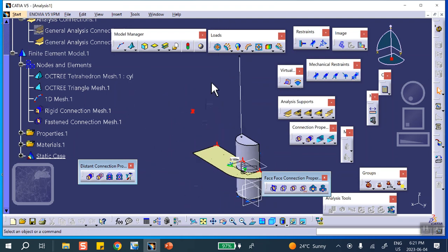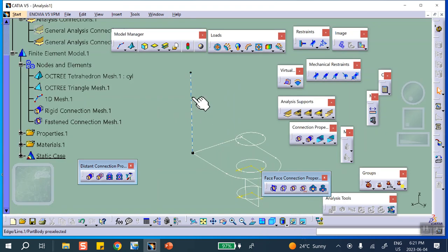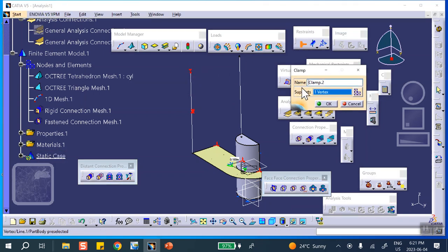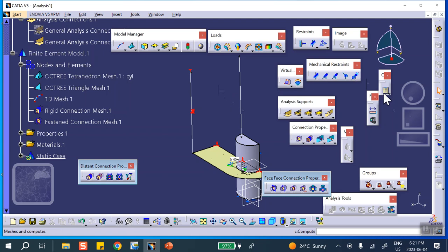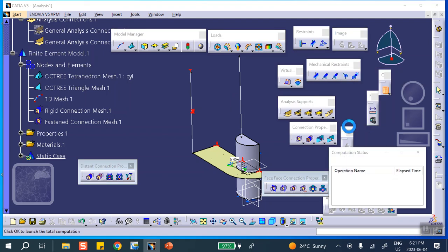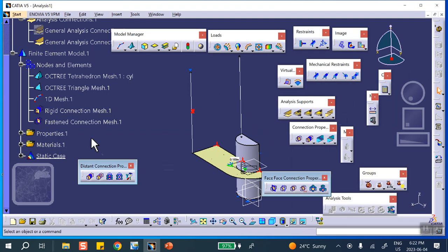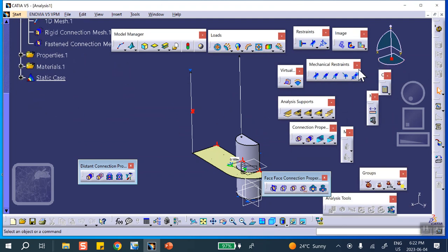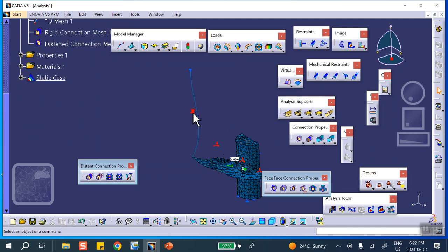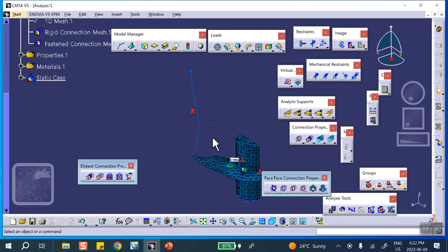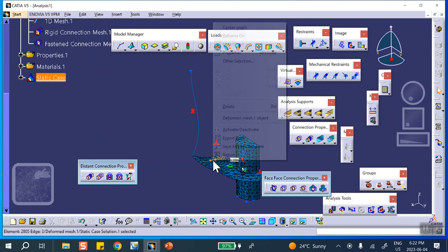Oh, we forgot to clamp. Okay. Where is that line? We forgot to clamp this line on the very top. That's why it says, hey, I'm not running. Right there. We forgot to clamp this. This thing doesn't lie. I mean, basically, we make a mistake usually, or I make a mistake. Right, right. Okay, so let's look at the deflection. Yeah, okay, you can see it bent. Yeah, good, good. Now, if I want this thing to be a cable, then let's deactivate that.